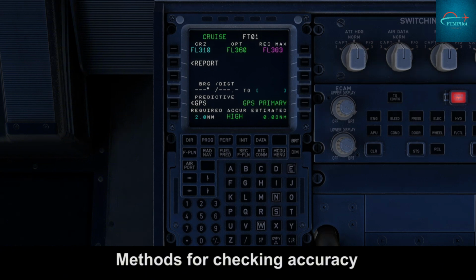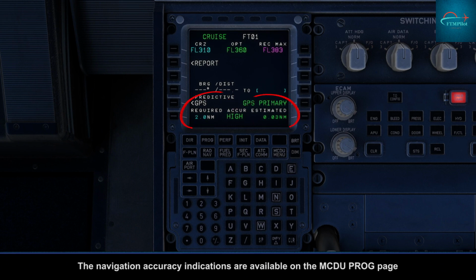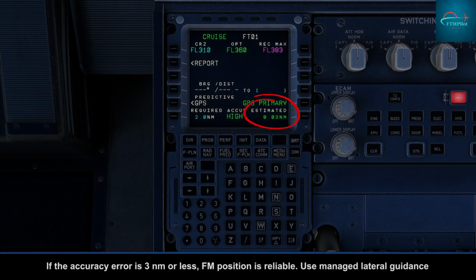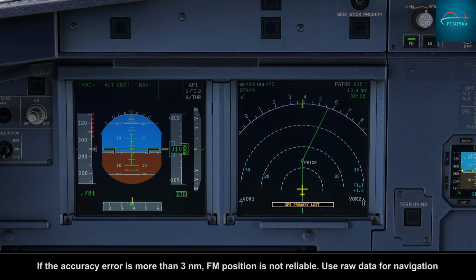Methods for checking accuracy. The navigation accuracy indications are available on the MCDU progress page. If the accuracy error is 3 nautical miles or less, FM position is reliable. Use managed lateral guidance. If the accuracy error is more than 3 nautical miles, FM position is not reliable. Use raw data for navigation.